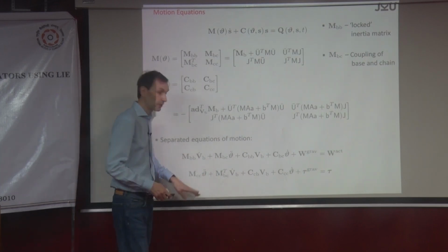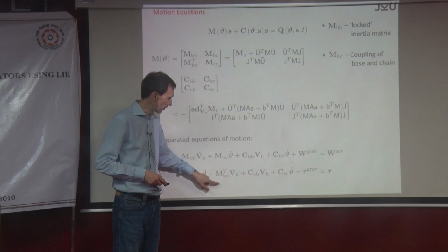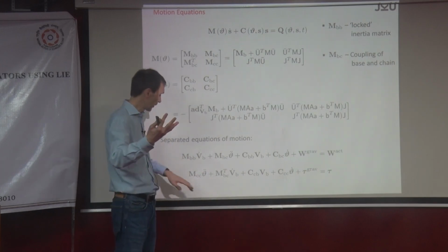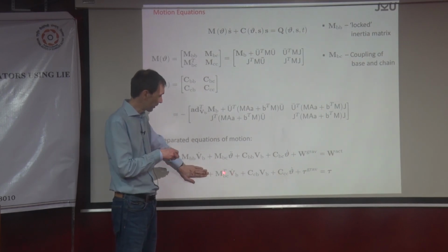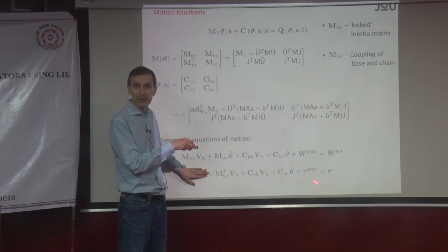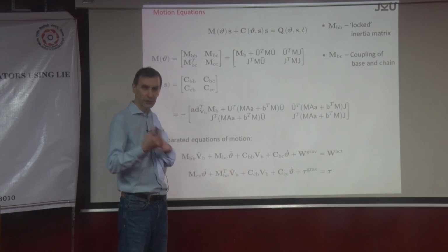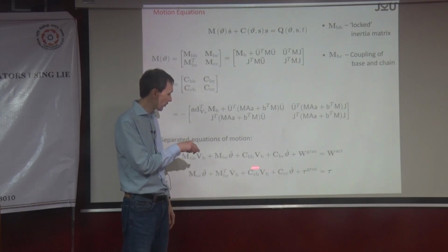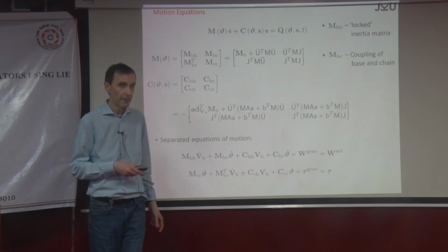Anyway, there are applications for this. You get this by looking again into the special case, and we always look at this cross coupling. So when I say the robot is not moving, the joints are locked, then this goes away and that goes away, and we are left with this one. What it gives you are the joint torques that you need to hold the system as it is when the base is doing a motion with the base twist VB, okay?